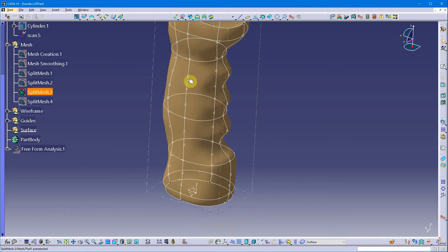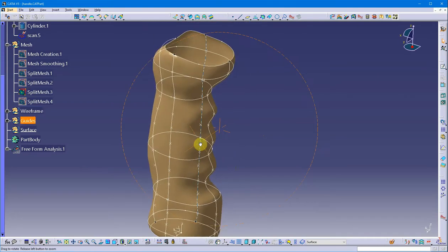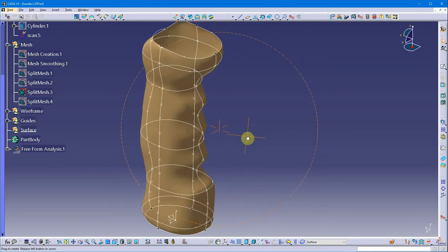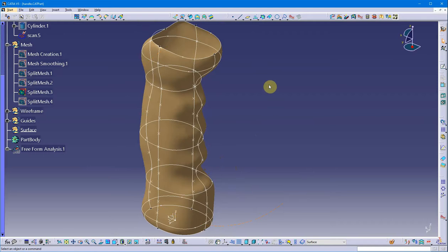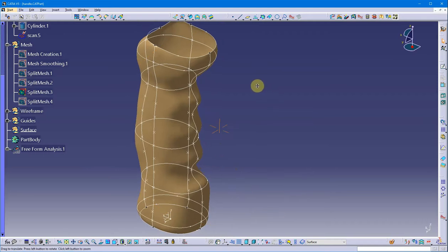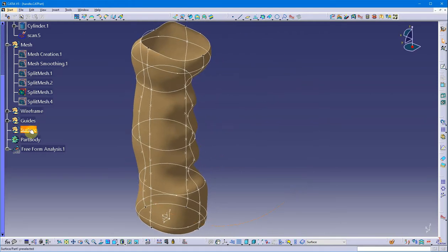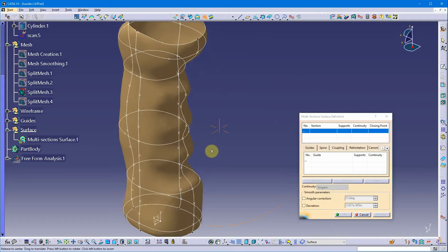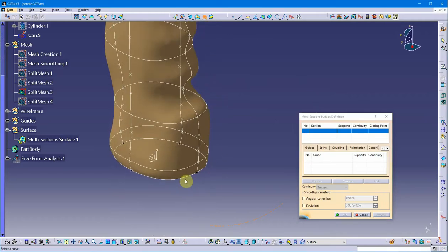These are scans, they're now curves that I created with free edges. I'm just going to use those right now for my lofts. And then I'm going to show you what it looks like and then come back and improve that just a little bit. So I've got a geometric set called surfaces. I'm going to use the loft tool here. So I'm going to go in and just create a real quick loft.